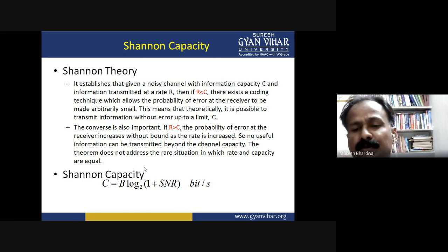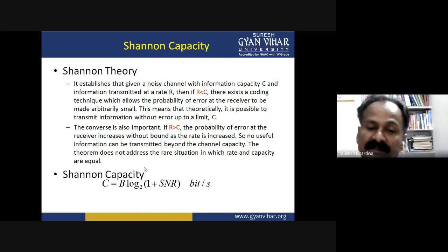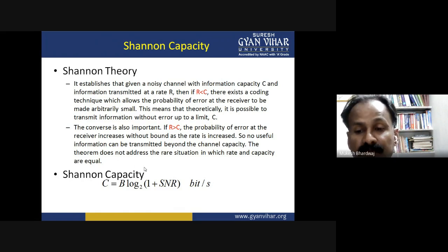For example, point to point channels are wire lines, microwave links, and optical fibers. Wire lines operate by guided electromagnetic waves and are used for local telephone transmission. In microwave links, the transmitted signal is radiated as an electromagnetic wave in free space. Microwave links are used in long distance telephone transmission. An optical fiber is a low loss, well controlled guided optical medium. Optical fibers are used in optical communication.